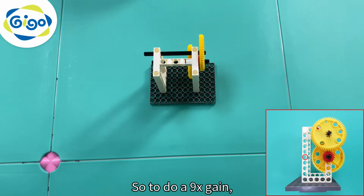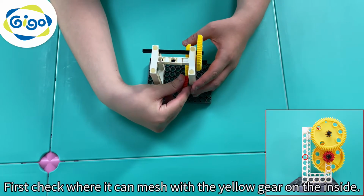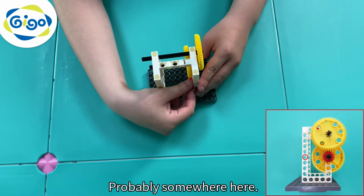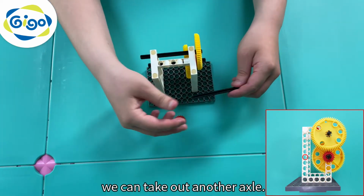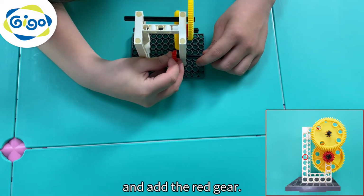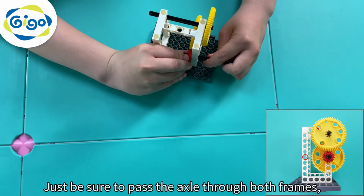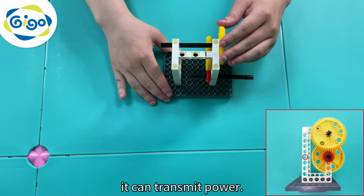So to do a 9x gain, take out another red gear. First check where it can match with the yellow gear on the inside, probably somewhere here. After confirming the position, we can take out another axle. Thread it through the correct hole in the frame like this and add the red gear. Just be sure to pass the axle through both frames, because we need to make sure that it can transmit power.